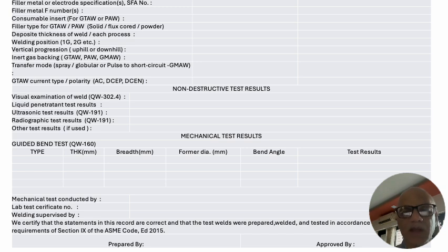It is not like a mechanical joint where you unscrew, replace the gasket or replace the o-ring or replace the bearing or refit and retighten it. It is not as simple as that, because it is associated with heat. It has its own heat affected zone. It has its impact on the metallurgical characteristics, on the grain growth or any other dendritic growth which are anchored. The distortions are very high, so even if you are successfully able to repair it, the distortion will kill your job for not meeting the dimensions.